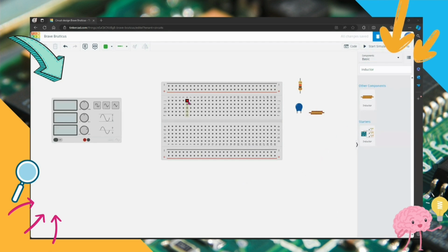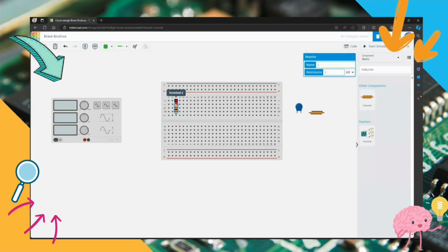So now let's continue. One more thing I want you to understand is that if we connect any element, supposedly I connect a resistor like that, then in that case it will be shorted, because I already told you the voltage across these points is the same. So if you connect any element like that across the same points, that means the two terminals have the same potential, so it will be shorted and it will not work. So instead of connecting like this, we will rotate the element and make the connection like this.